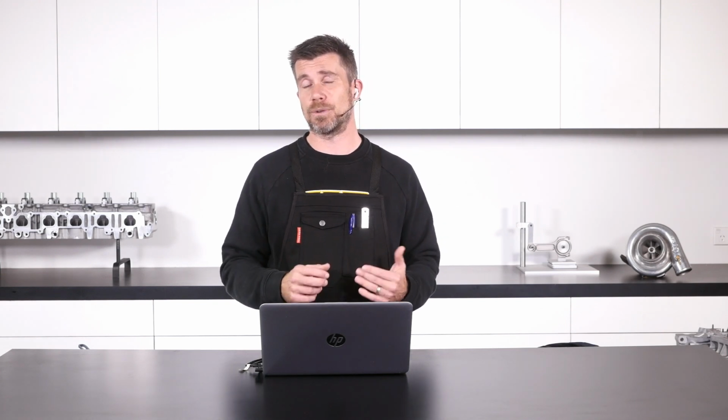But basically what we're talking about here is the back pressure that is between the exhaust ports on the cylinder head and the inlet to the turbine housing or turbine wheel on the turbocharger. So while yes, we will have some level of exhaust manifold back pressure on a naturally aspirated engine, generally when we are referring to EMAP or turbine inlet pressure, it is as a result of some analysis that we want to do for a high-end turbocharged engine.